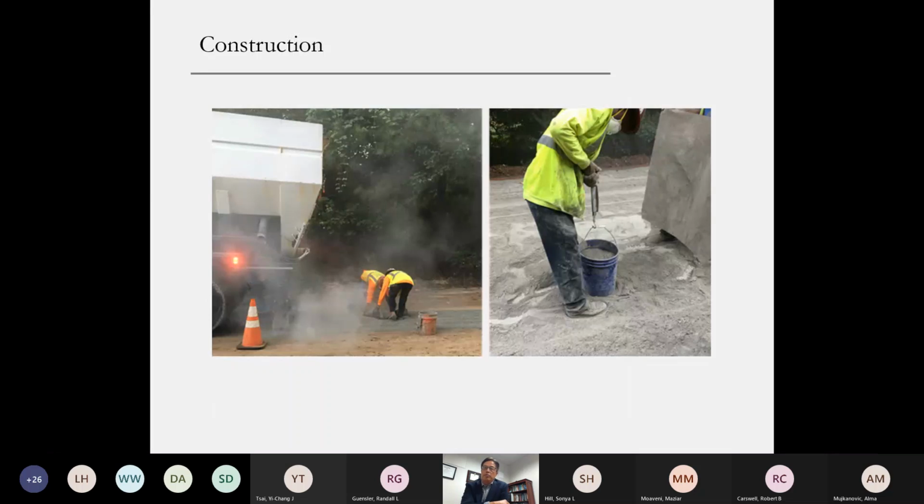On the day of the FDR process, the dry cement is placed, and then the amount of dry cement was validated using the square yard cloth method. Basically, you place a square yard of fabric, collect the cement placed on that square yard of fabric, and then measure it to verify that the target dry cement content was placed. This is not very scientific, but it seems to work great.